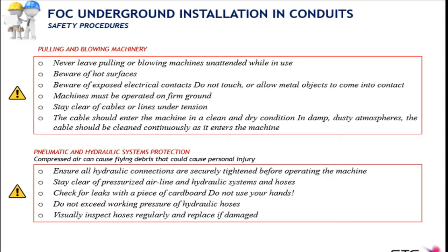Otherwise, when you fire up the equipment, those can kind of explode and hit you, causing some damage to you guys. So this is about making sure that all connections and hoses in pneumatic and hydraulic systems can operate and are properly connected before you start working with equipment.